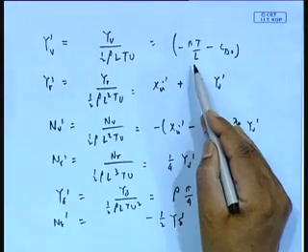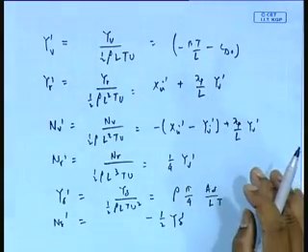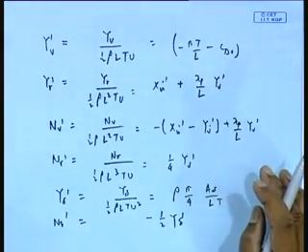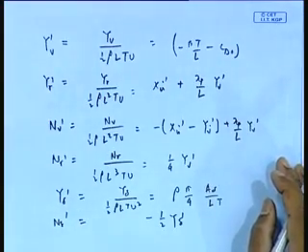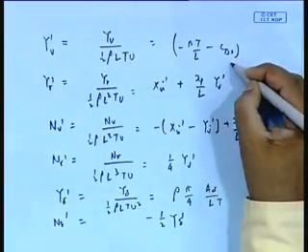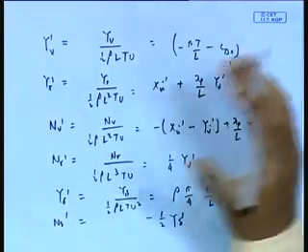If you look at that, it is exactly the same as what we have done in the last class based on slender body and strip theory approximation. But there is a difference. They use this CD0 term. Basically, it is a modification using this drag part, because in slender body also we actually did not take this CD0 part. Actually, it should be CL cos alpha minus CD sin alpha, etc.